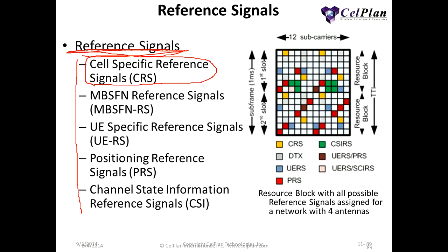You know the content of the signal, so by knowing what was sent, it's easier to adjust for the losses and distortion of the RF channel. So I am supposed to receive X, so let's move my gain and my phase until I get X, and then you know how to adjust for the RF channel at that subcarrier, at that symbol, at that resource element, and then for the other ones, you interpolate between the reference signals.